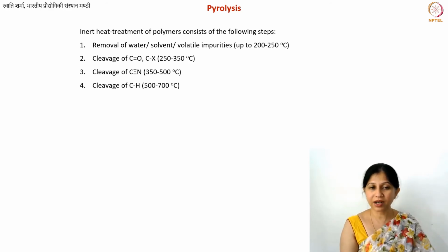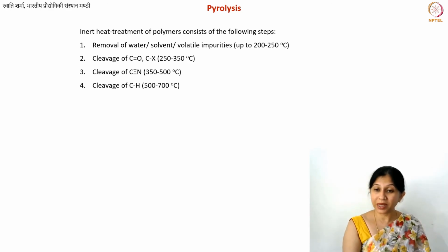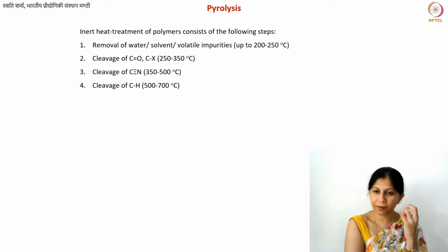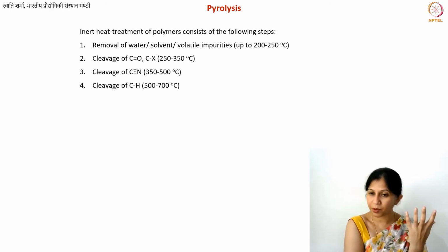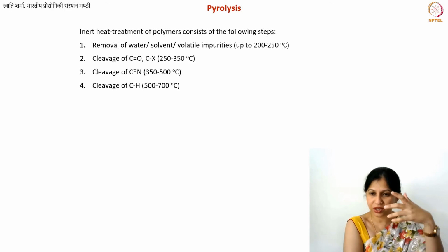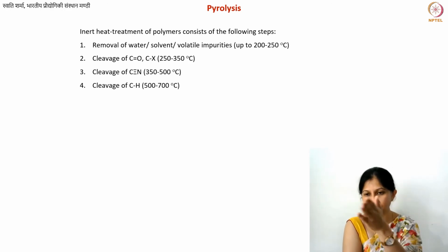So up to 700 degrees, you will have most of the hydrogen bonds breaking, which means that your polymer will break into smaller and smaller fragments. Some of these smaller fragments, without further individual bond breaking, will just leave your material, because you have this nitrogen pushing them anyway.